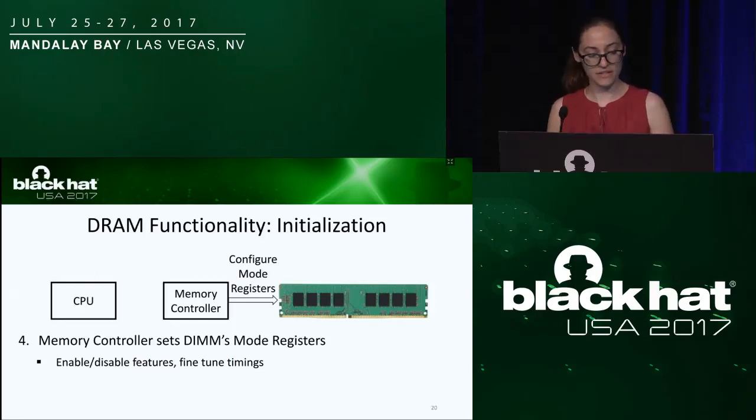And the final step of the initialization is that the memory controller needs to set the DIMM's mode registers. Those are registers that are held on the DIMM, and they're used in order to enable or disable features or to fine-tune some of the timings. So if you, say, want to overclock your system, those are the registers that you need to poke at, or let the BIOS do it for you.